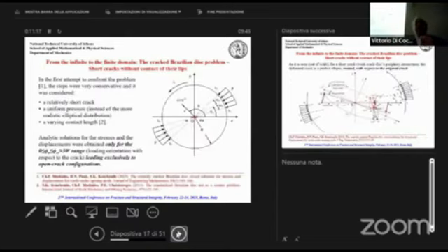When we started dealing with the cracked finite disk, two problems together, finite domain and cracked disk, we were very conservative. We considered initially a very short crack because we wanted to avoid interaction of the crack with the boundaries of the problem. And also, we considered a distribution, not point load, a distribution of stresses along a varying contact length. This is perhaps the innovation.